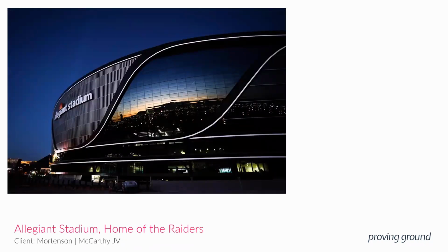We also had an implementation of Conveyor to support some of the production being done on the exterior facade of Allegiant Stadium, home of the Raiders in Las Vegas. Our Conveyor Toolkit became a device for Mortenson McCarthy, the general contractor, a joint venture general contracting effort, to take objects from Rhino, provided by their facade design assistant and their architect, and bring them into a Revit environment, so it could be used as a kind of level 300 model for design sequencing and coordination. So they took imported Rhino elements into Revit and turned it into a way to coordinate the installation